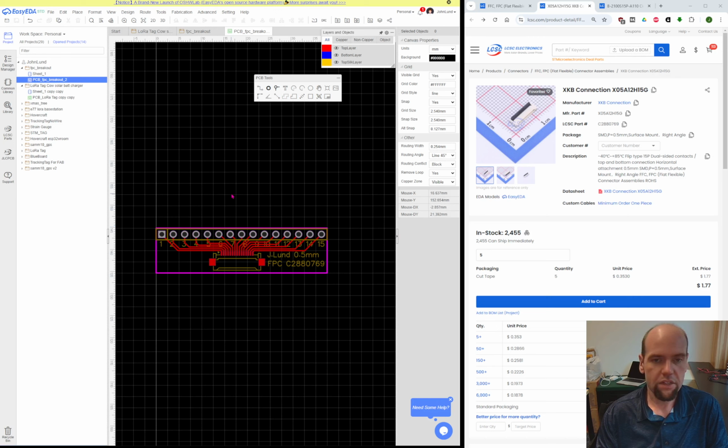Okay, and so now it downloaded it. And that zipped up file is really all I need. I might do another video where I show you how to check it. But basically that zipped up file has all the Gerbers that a fab would need to make this thing. So we're pretty much done.